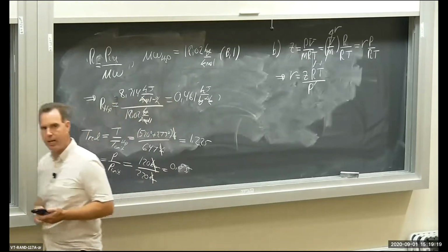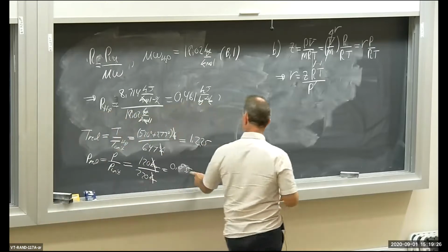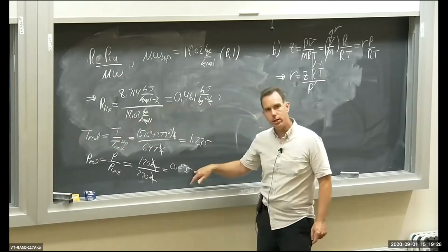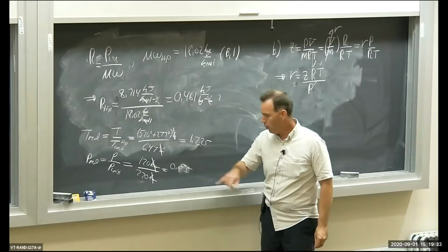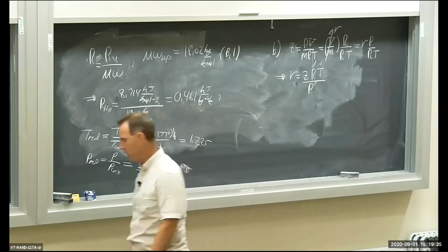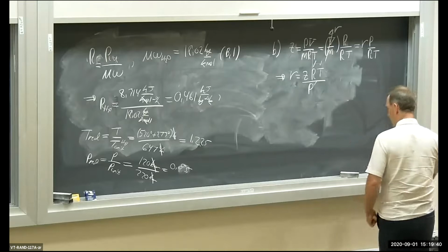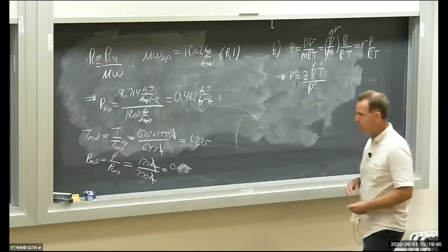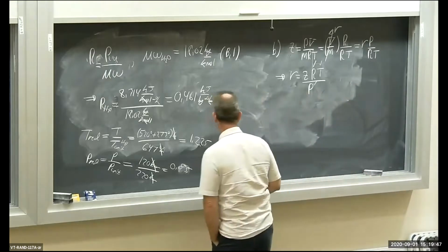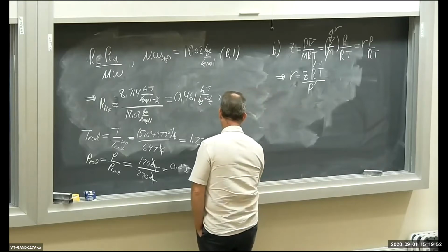By the way, if you're thinking ahead on using the ideal gas law, where Z is approximately equal to 1, we're already in trouble here. Remember the criterion for using the ideal gas law is reduced pressure must be less than 0.2. We're at 0.55, almost 0.6. So clearly for part C, when we calculate specific volume based on the ideal gas law, we're probably not going to get a good result. In any event, reduced temperature and pressure, 1.2 and 0.5.